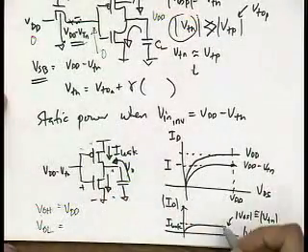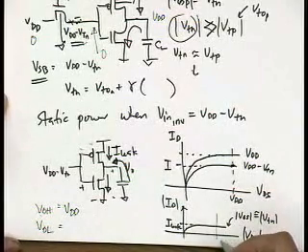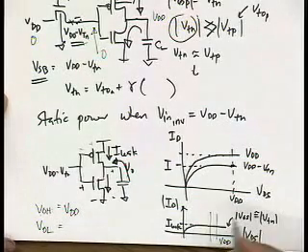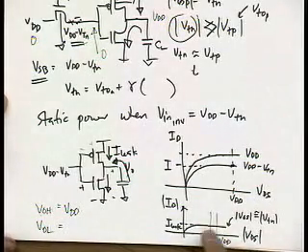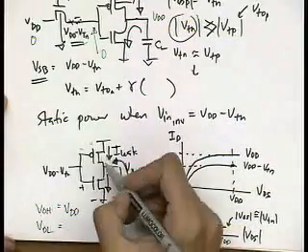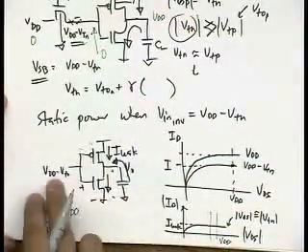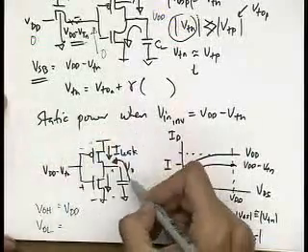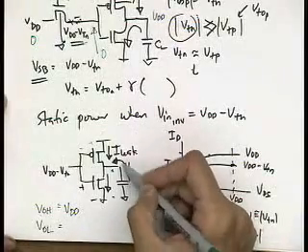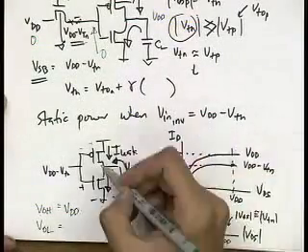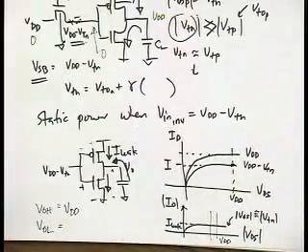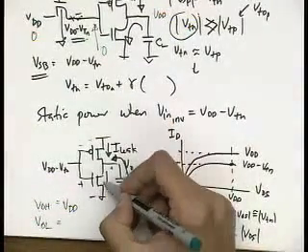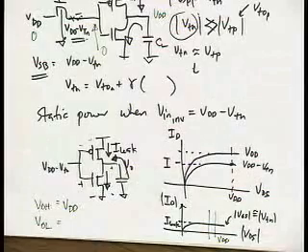It means that the VDS of my PMOS would be very close. If this is VDD, it'll be very close here. You have the same currents, depending on channel length modulation or whatever. So during static operation, when this is high, and after you discharge most of the charge, the current passing through the capacitor will be 0. That's when you have static conditions. You have 0 current through your capacitors. This leakage current will be equal to the current passing through your NMOS.